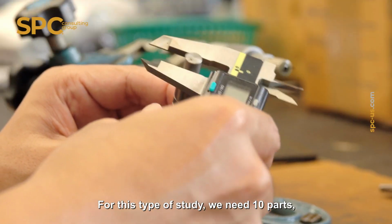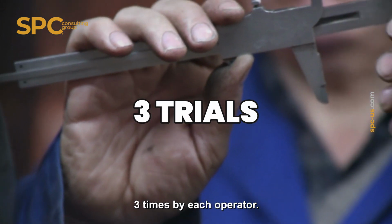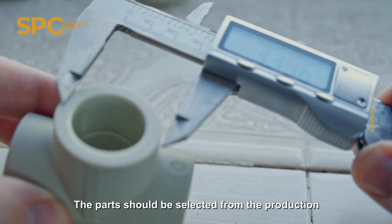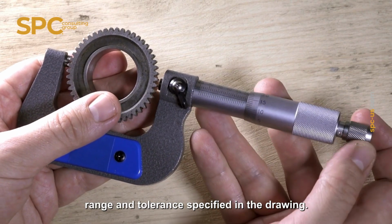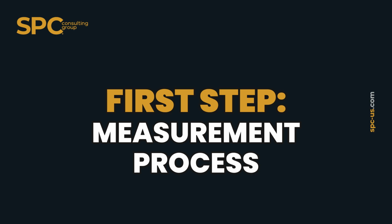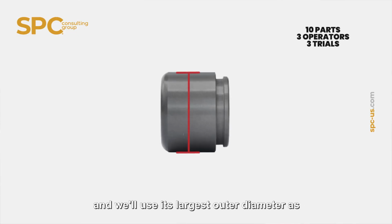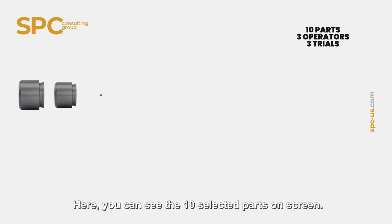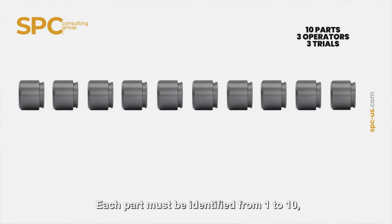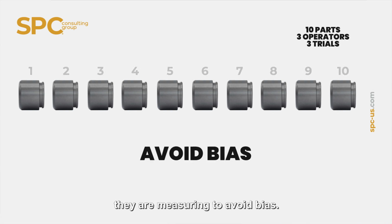For this type of study, we need 10 parts, 3 operators, and each part must be measured 3 times by each operator. The parts should be selected from the production process, ensuring they cover the full operating range and tolerance specified in the drawing. First step, measurement process. In this example, we're working with a piston, and we'll use its largest outer diameter as the critical characteristic. Here, you can see the 10 selected parts on screen. Each part must be identified from 1 to 10, but without marking them directly, as operators should not know which part they are measuring to avoid bias.